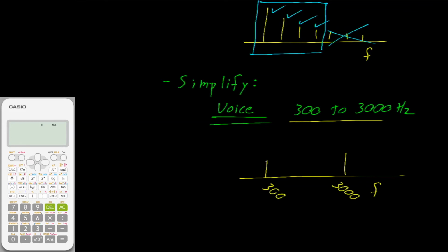In fact, you'll often see me do this. I'll simply describe voice as a wedge of frequencies between 300 and 3000 hertz. With this simplification, we can run a calculation at 300 hertz. We can run it again at 3000 hertz. If it's good on both ends, we can have some confidence that the stuff inside will not be changed. This wedge of frequencies will become very important to us soon in our discussions of modulation.